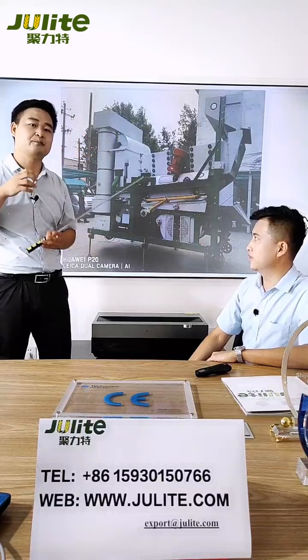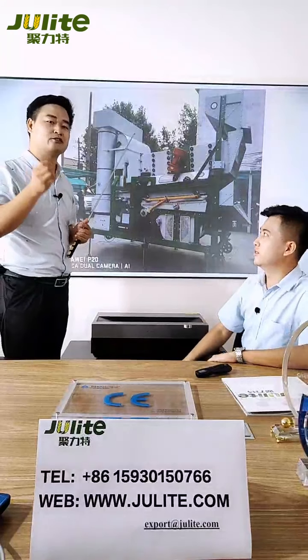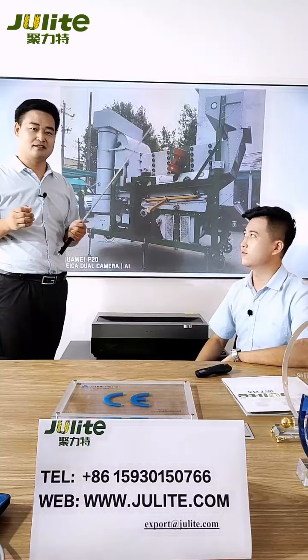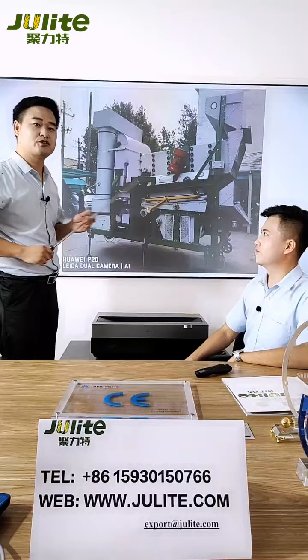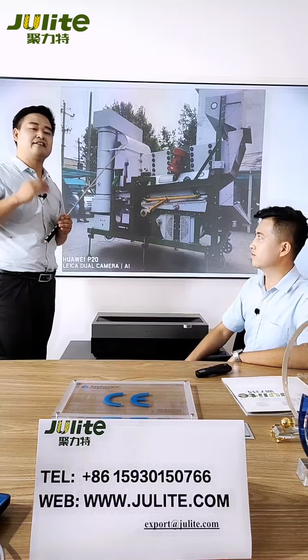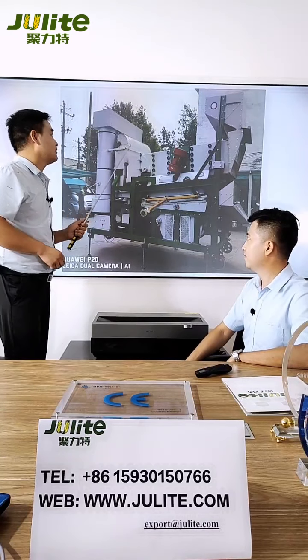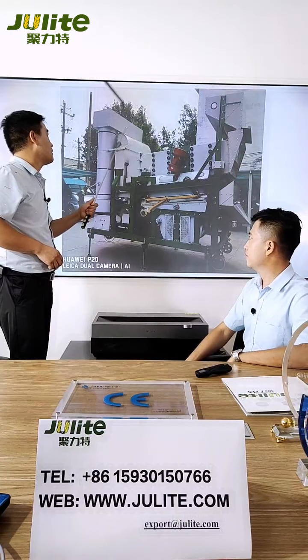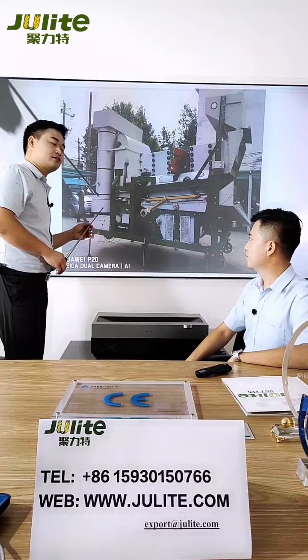The dust impurities from this part go into the air duct, then into the cyclone. The dust and the light impurities, maybe including light leaves, sticks, leaves, and maybe insects, go into the cyclone. Then they go through the air lock valve and go outside. And the clean wind goes out through this square duct, this pipe, and the fan.